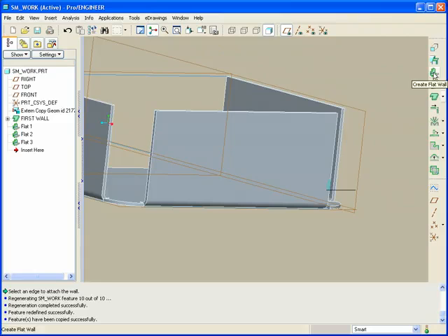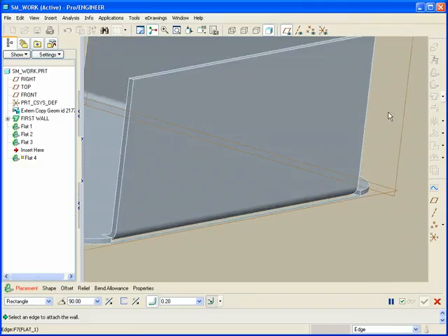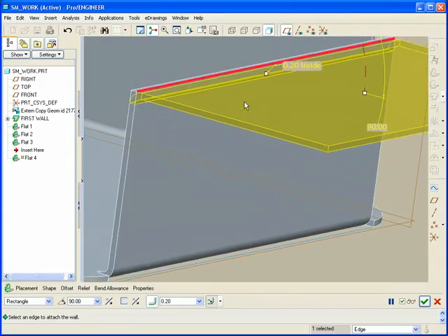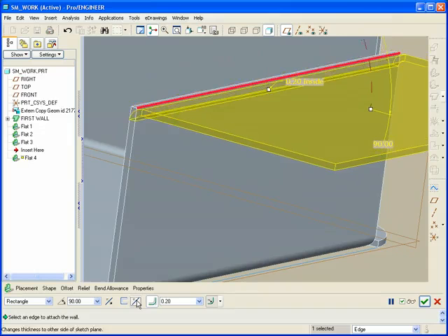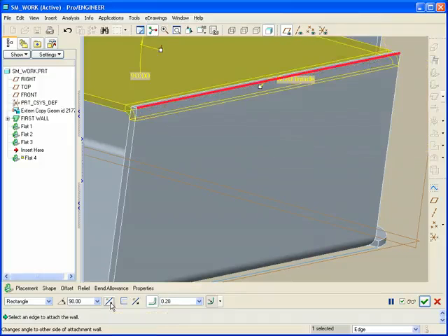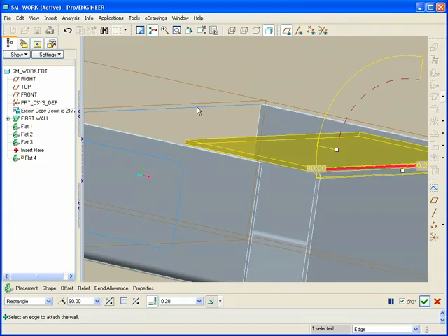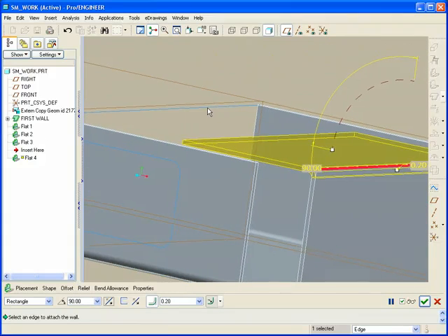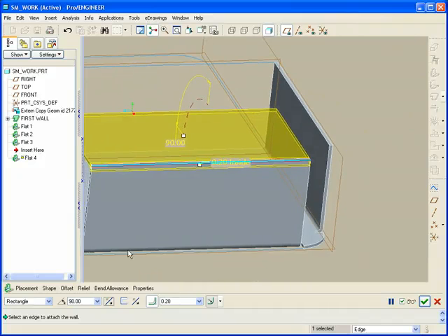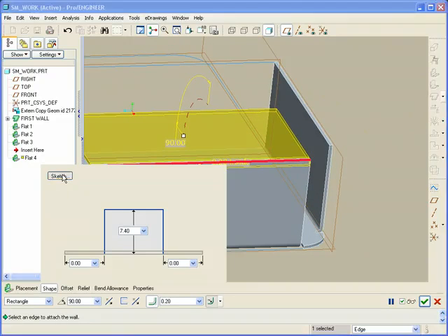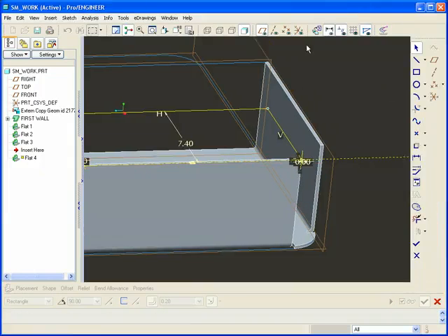Now I'm going to make another wall connected off to this edge here, flipping again inside the outside face or outside dimensions, and then going inside so that the top definition is defined by this curve. Now this wall needs to have a very specific shape too, so we'll go straight into its sketch,